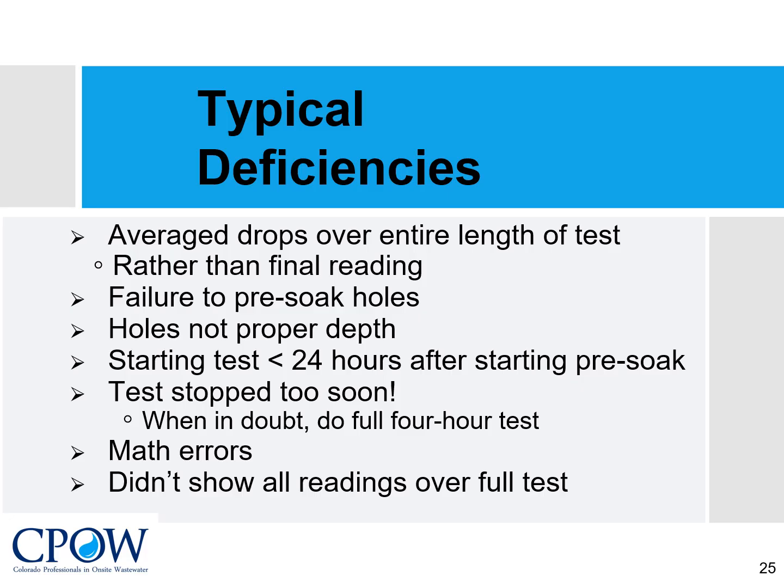Starting the test less than 24 hours after starting the pre-soak can also cause inaccurate rates, as well as stopping the test too soon. When in doubt, do the full hour test. We also see inaccuracy from math errors and not showing all readings over the full test.